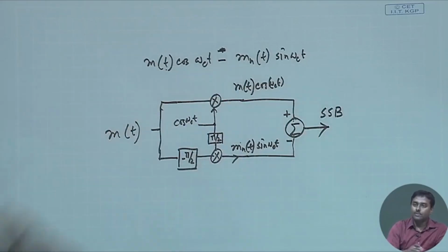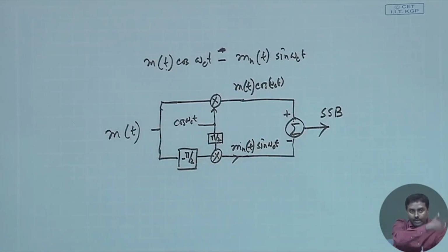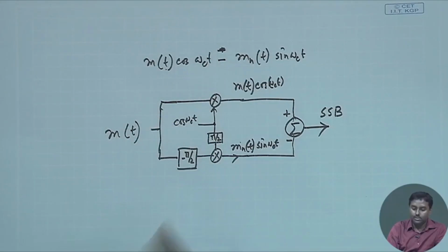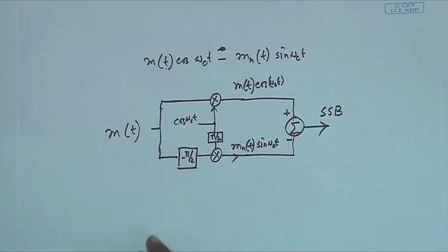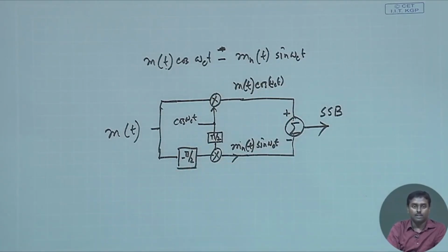So that is the easiest way we have understood. The modulator has been defined just by knowing that mathematical understanding. You wanted to generate that, and you immediately understood that it is nothing but this. So I need to do this m_h(t), and you devise a Hilbert transform circuit. Once you have that, it is nothing but two modulators and one Hilbert transform.